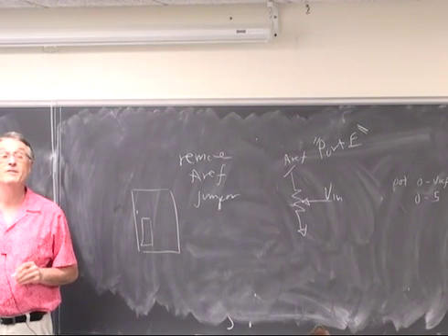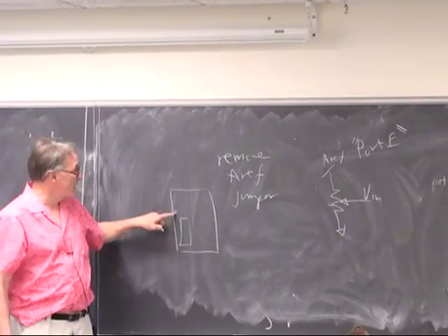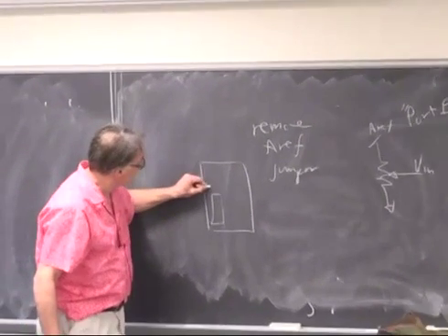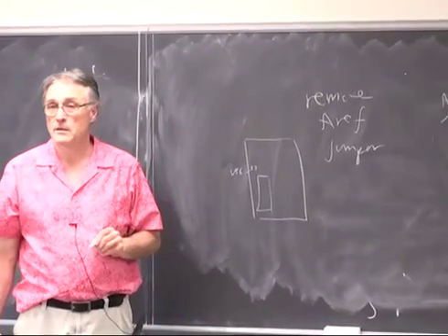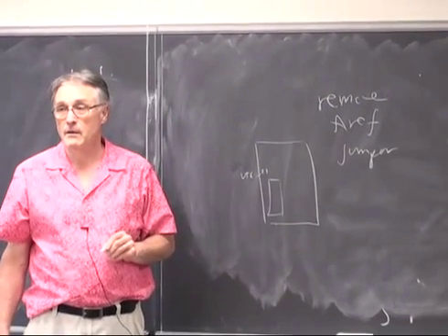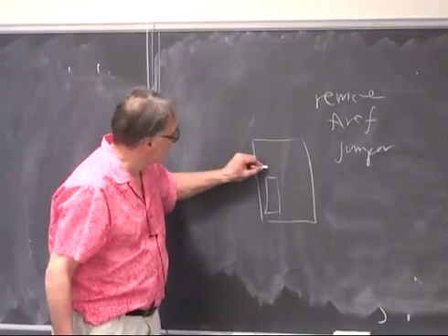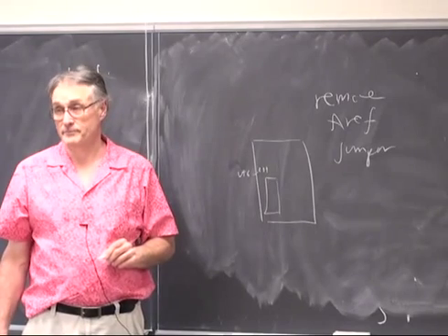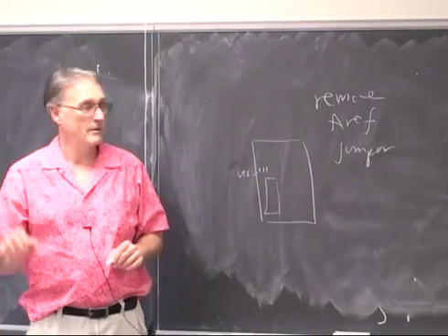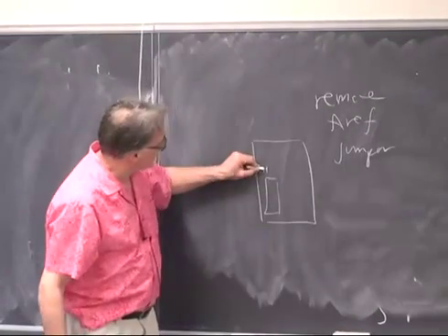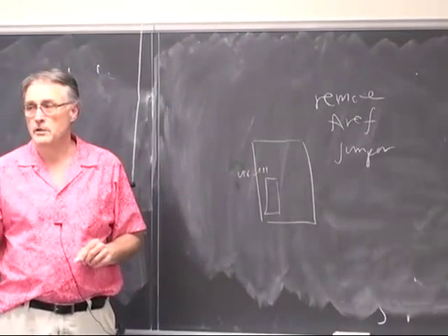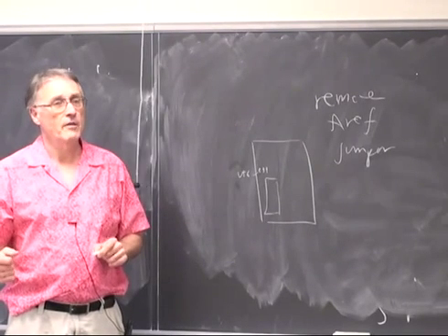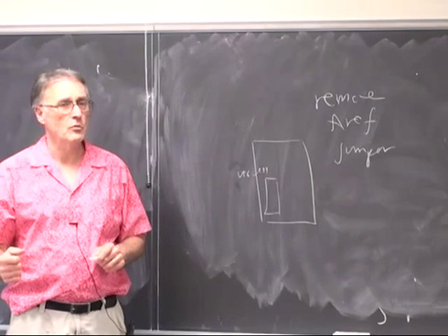You better look at those every time you pick a board out. That's V target. That's VCC. So this is VTG. The next jumper is AREF. The next jumper is reset. Then clock. They all have to be there. Except in this case, you're going to unmount AREF. You have to unmount AREF. Otherwise, you'll say, that's funny, my auto scale doesn't work.